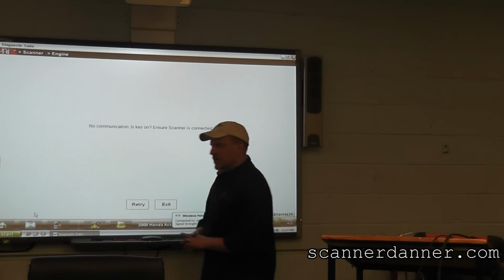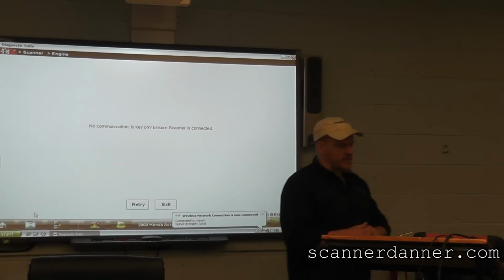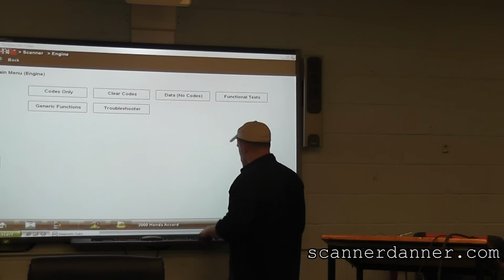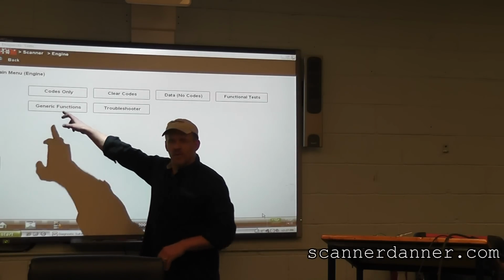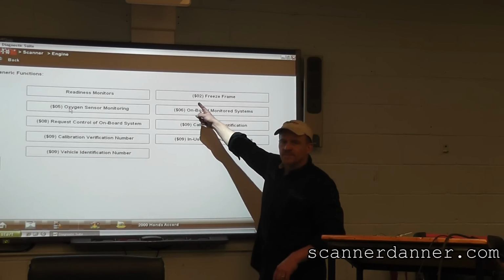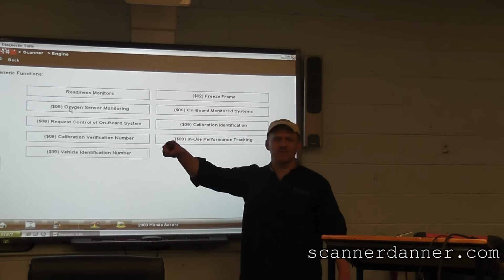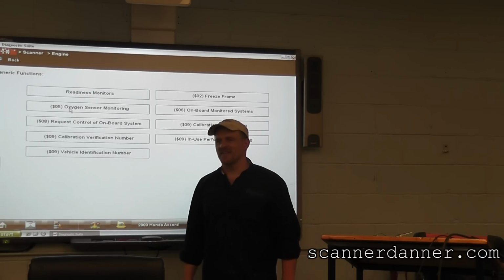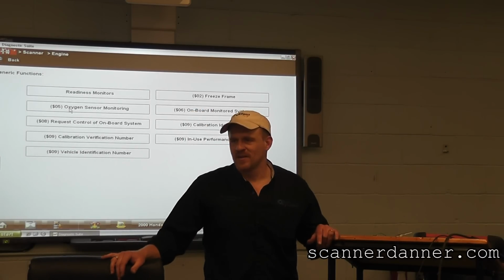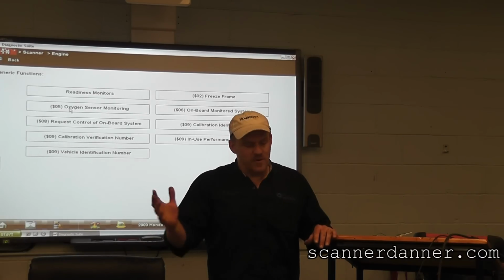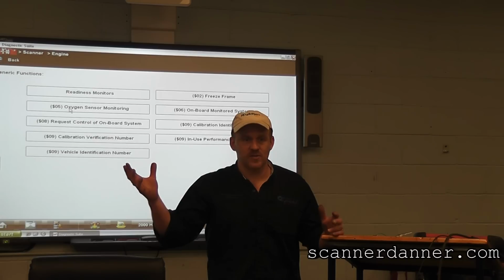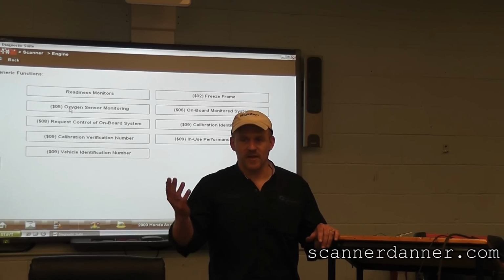Okay, so here's what we want to do, because I want you guys to see the trim numbers, and we can come back to that maybe. To see trim, we had to go, can we go generic functions? Yes. We can't. Where's mode 1? That's why it's called generic functions, not global OBD2. It's not the full list. I don't know the reason, but I have data in the manufacturer mode. I guess they assumed you don't need the global data. They don't give it to you.